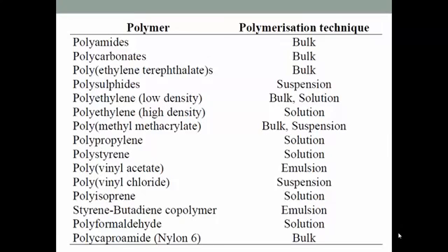Therefore, a polymer with a high degree of polymerization is obtained, rather than that obtained by bulk polymerization or suspension polymerization, as the heat released by the polymerization is absorbed by the water around the micelle in emulsion polymerization. So it is easy to adjust the temperature like suspension polymerization. The generated polymer obtained in emulsion polymerization is used for various purposes such as paint, textile treating agent and adhesive without any change. Although salts are added, it can condense and solidify and the polymer can also be produced